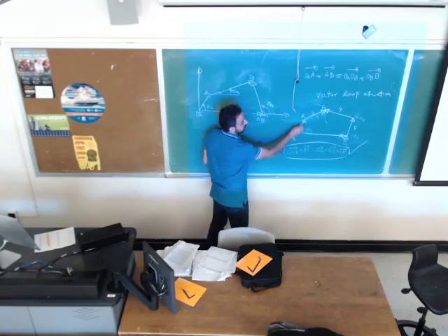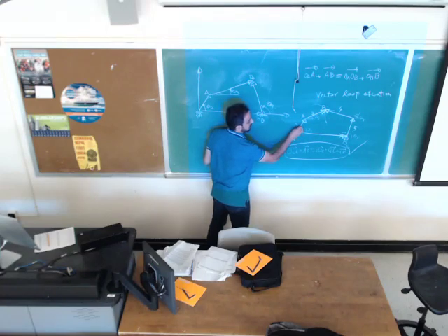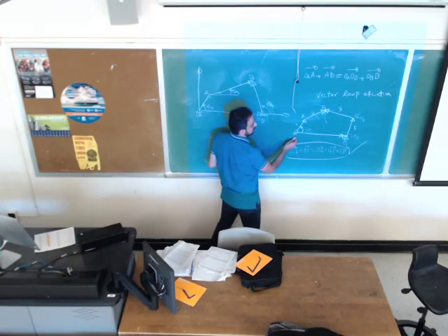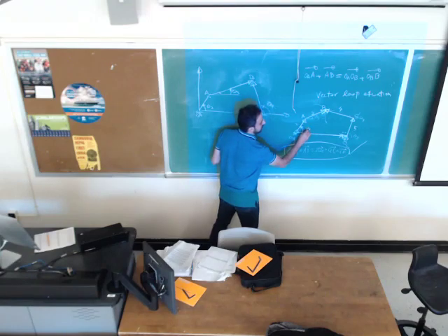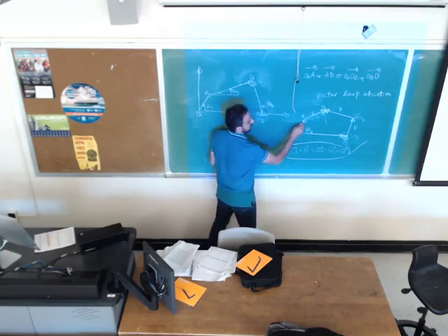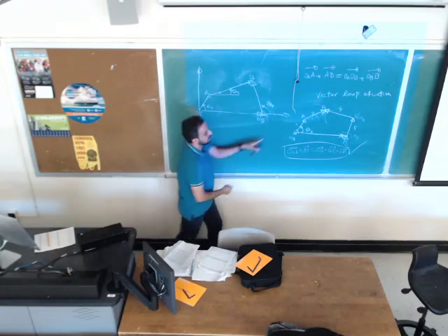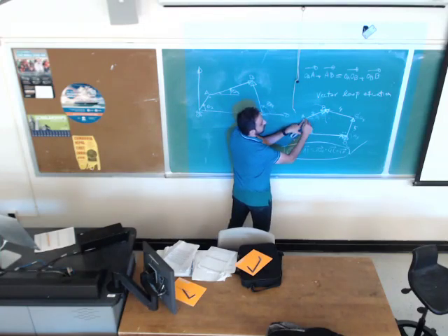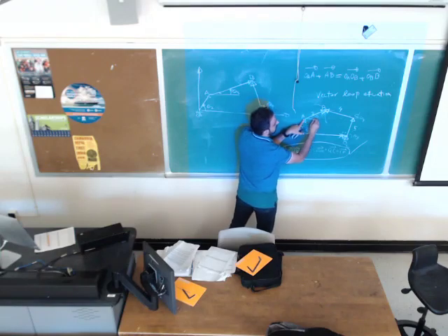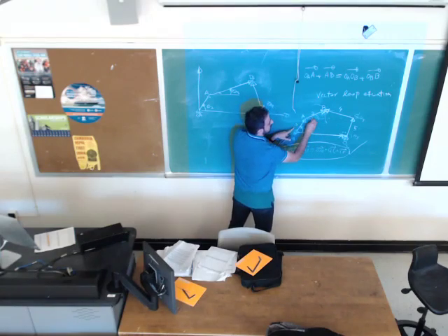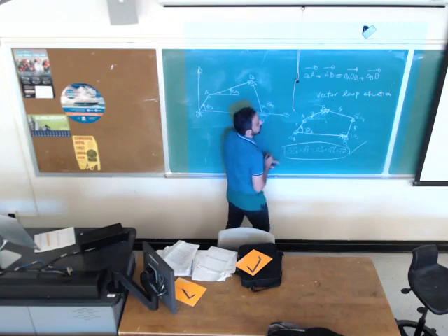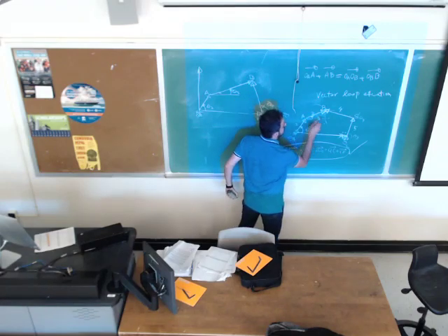At the starting point of the vector, measure the angle from the ground, moving in the counterclockwise direction. Theta 2 is going to be this. The 2 represents the number of the link. Link 3, you should measure theta 3 at point A, not point B. Draw a line parallel to the ground, measure this at point A. This is theta 3.